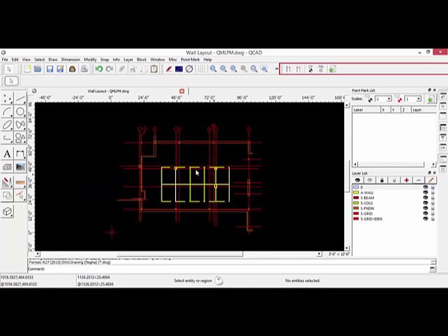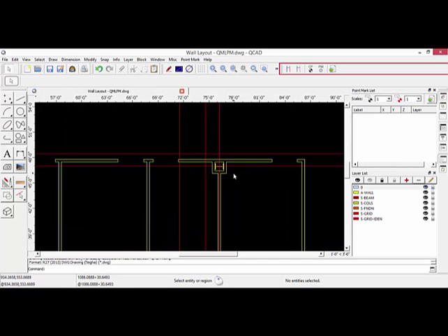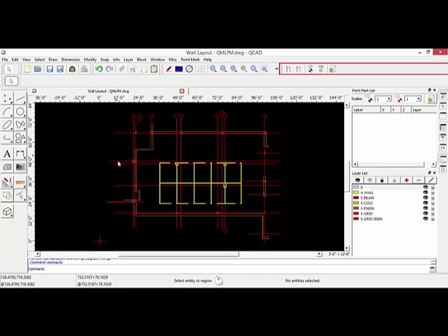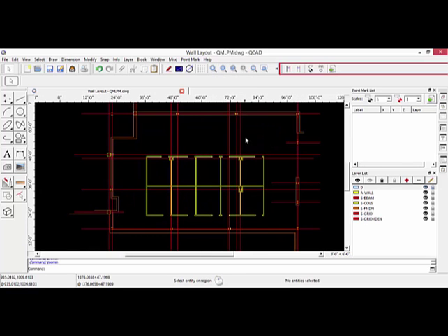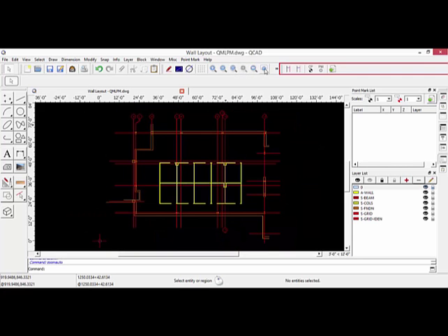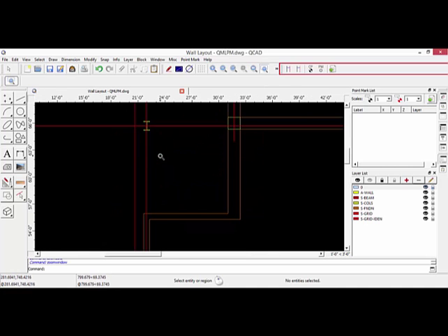You see a couple of little commands in here. If you are zoomed in and you want to come right back out to the overall drawing, you use this icon right here, which is auto zoom, and it'll do a zoom all to everything that you have in the space. There's a zoom in or zoom out if you want to use these. These are just stepwise instead of the actual wheel. You do have a zoom window as well and a zoom previous. If you say zoom window, you can pick 2 points and zoom into that space to get closer in there.